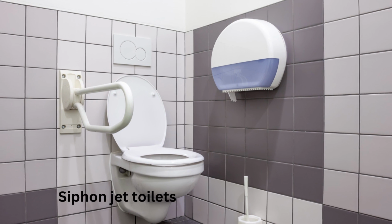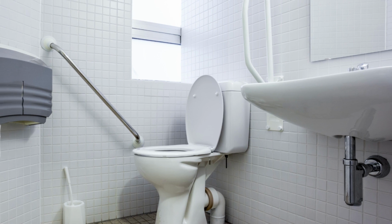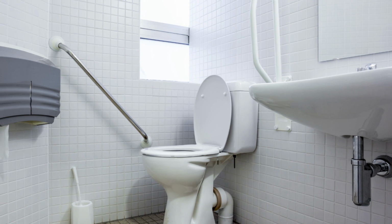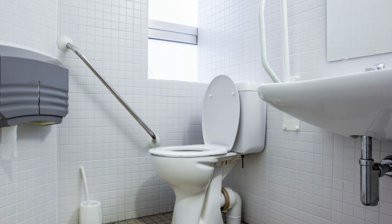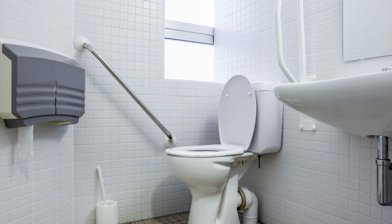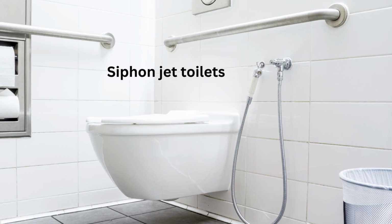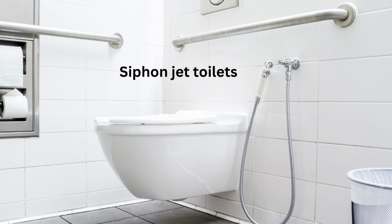from the bowl. Unlike gravity flush toilets, which rely on the weight of water to move waste down the drain, siphon jet toilets use a combination of water and air pressure to create a strong suction that pulls waste from the bowl. The design of a siphon jet toilet includes a rim with small holes that distribute water around the bowl when flushed. This creates a vortex of water that pulls waste towards the bottom of the bowl.